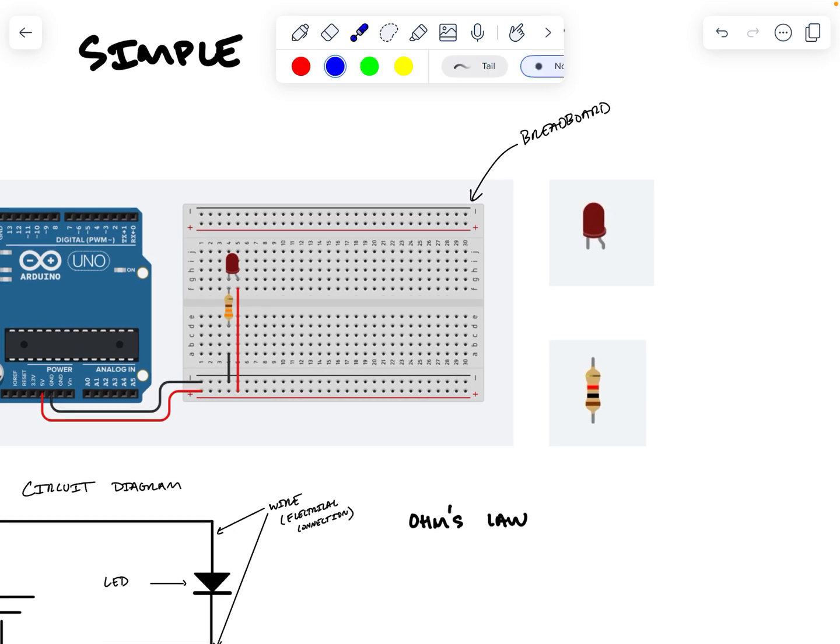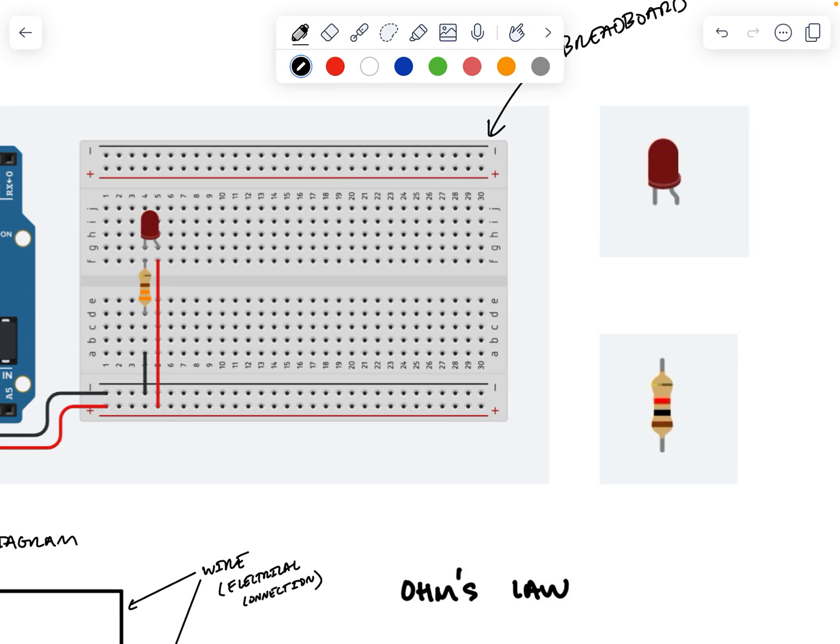If you take the breadboard, flip it over, and peel off the sticky foamy backside, which I don't recommend doing because it can be hard to put it back on, but maybe just peek a little bit, you'll notice that you can see these metal bars underneath the breadboard. And this shows you how all of these little wells of the breadboard are electrically connected to one another. So for example, in the orientation of the breadboard I have now, this is a column.